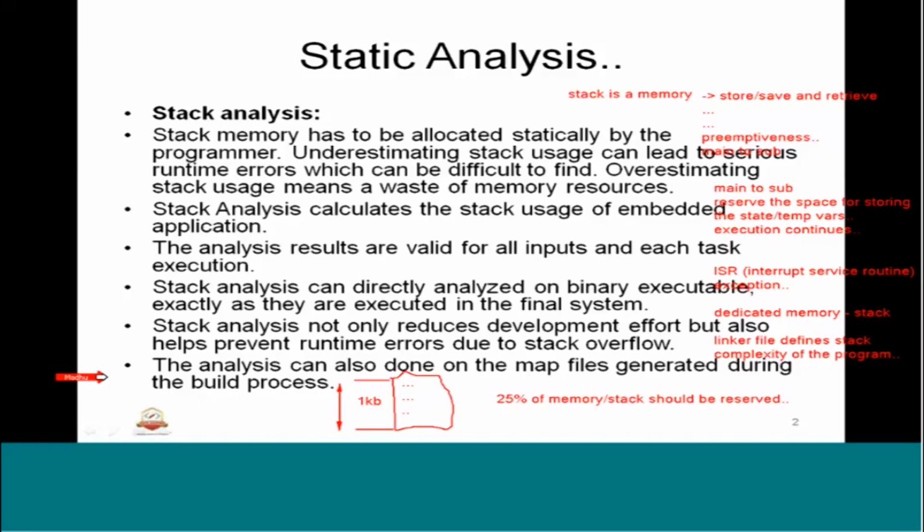Preliminarily, the analysis can be done on the map files generated during the build process. That means once we build, after the linking, we generate the map file along with the binary executable. The map file will clearly tell how much executable there is, where is the start, where is the end, and all that. Based on that, we can analyze the stack. So that is about stack analysis.